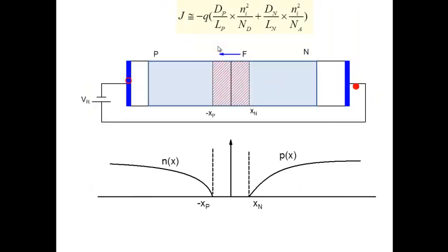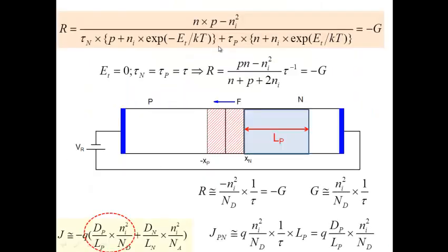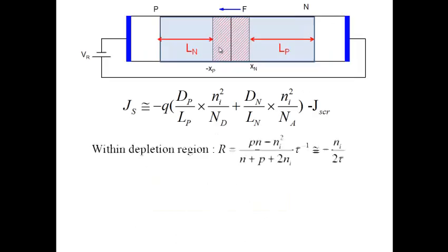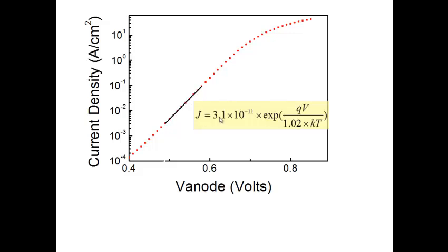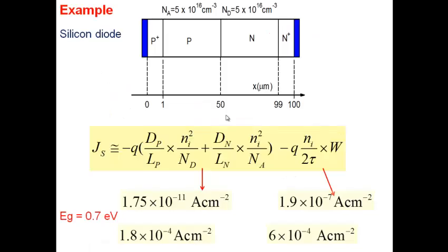So that is a point that's important in silicon and many other diodes, that the current that you get from here is just, this value is only for forward bias. It's not for reverse bias. Okay. It only indicates maybe the generation outside the depletion region here. So you need to go and measure the reverse current. Then only you will get this particular value. So the reverse current is going to be this value here, which is much larger than this particular value. Okay. And you can see here, in this case, is 4 orders of magnitude larger than this one.